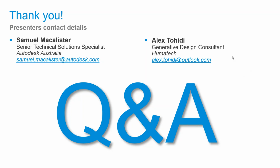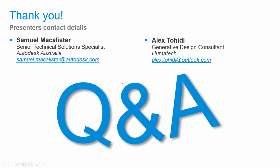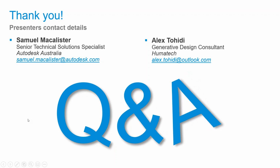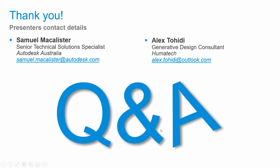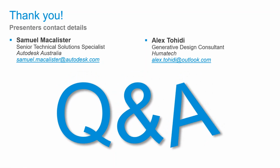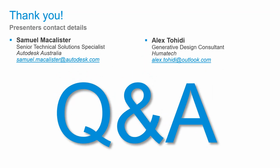Yeah, sure, Sam. So Alex was talking about using computational design methodologies for infrastructure applications. Some things that would apply to that include bridge design, for example. Me personally, I've been a Dynamo user for a little while. I've used Dynamo to select all of the bridge girders in a bridge model, for example, and then automatically count them and add mark values to each of those planks in the Revit environment.